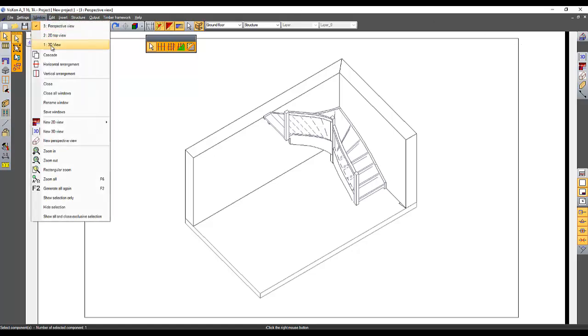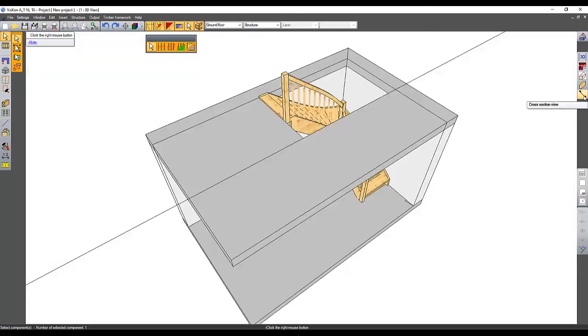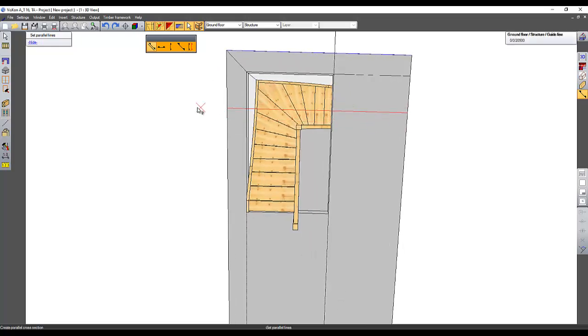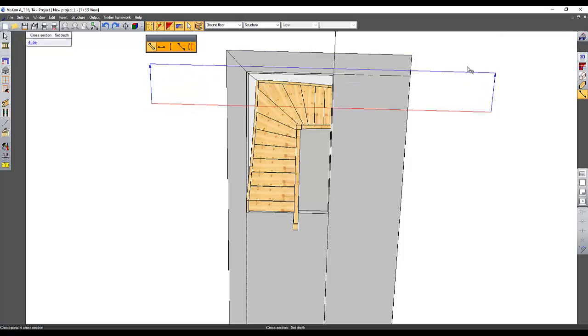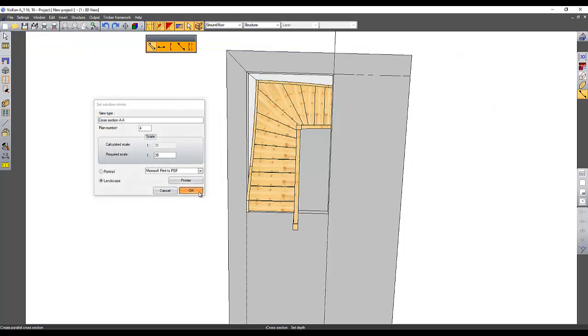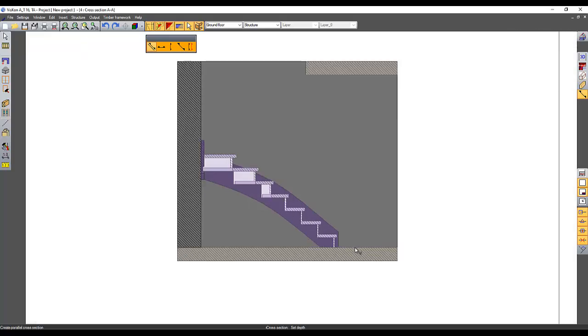And we're back in 3D, because directly here I will click the cross section button. I will take a reference for the cut plane. So I decide this. And in the middle of our stair, or the first wing, the first flight, I click here. On the left, on the right, this is the dimension of the section. We confirm it, the depth, and we have this situation.